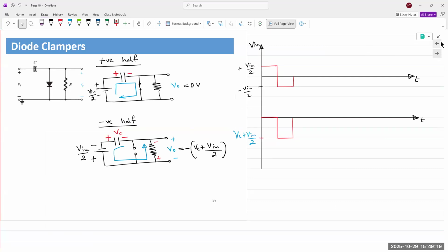Two back-to-back Zener diodes conduct in both directions. So if the input waveform is larger than the breakdown voltage, the Zener diode conducts, clips the rest of the circuitry. So you have a positive clipper and you have a negative clipper without using any power source. Those kind of circuits are used in voltage surge protectors. So if a surge comes in larger than 120 volts, it clips. The rest of it is not allowed to go through.